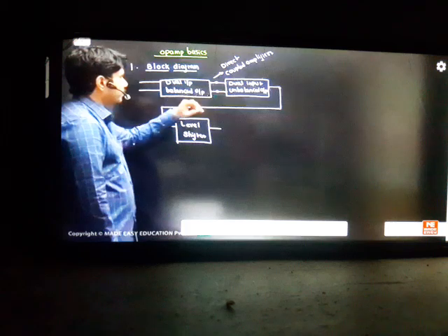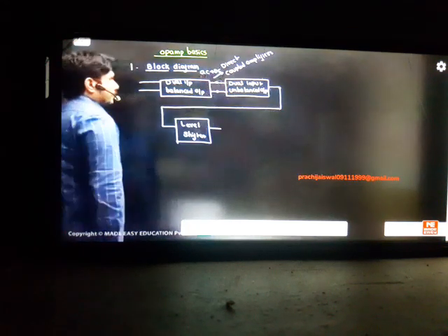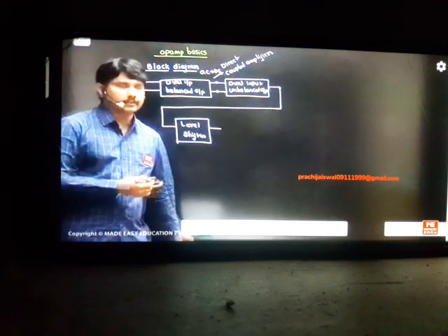If there is no coupling capacitor here, the problem is that this amplifier will give the output as AC plus DC. Generally, if you keep capacitors there, they will block the DC and give the AC output. But because you have taken direct coupling, as the size is small, you have to use direct coupling.